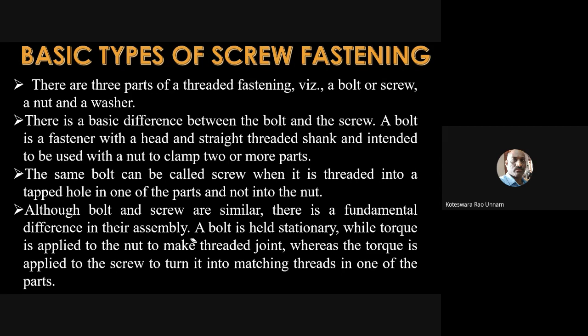So why do you need to apply it to the nut only? You can replace the nut very easily when compared to the bolt, or the cost of the nut is less when compared to the cost of the bolt. So if you tighten it more, if the joint will fail, that means the bolt will fail. Instead of the bolt failing, only the nut will fail. If the nut fails, you can easily replace that, because its cost is less.